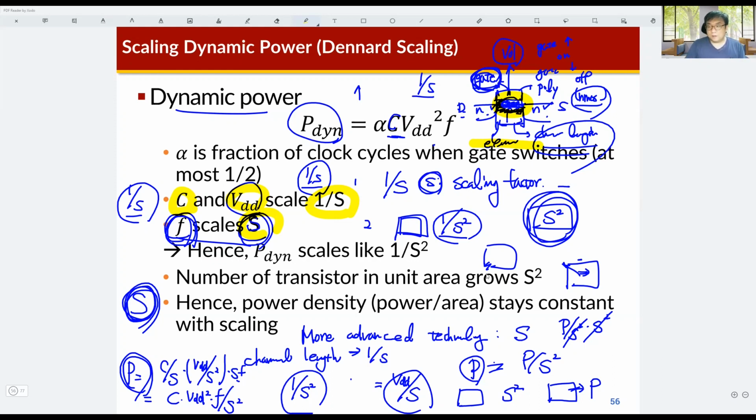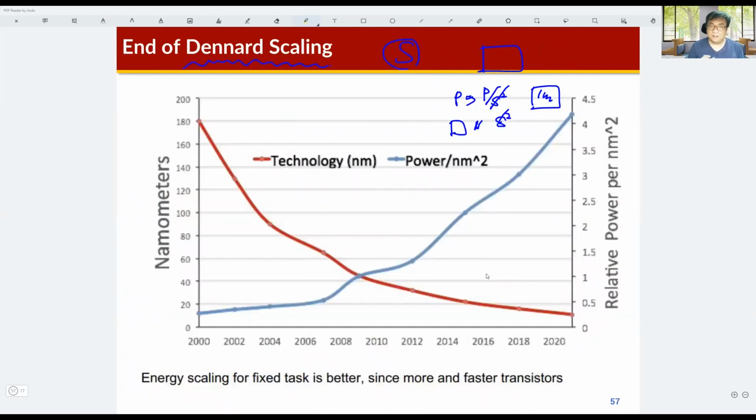If the Dennard scaling is maintained, we can increase the performance of the processor very easily by reducing the size of the CMOS transistor. But I mentioned that recently the Dennard scaling is not kept because of leakage current. If we increase the number of transistors in the same area, then this chip will consume more power. That means the end of the Dennard scaling.